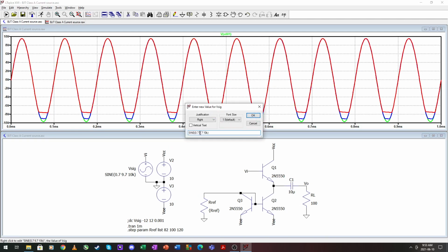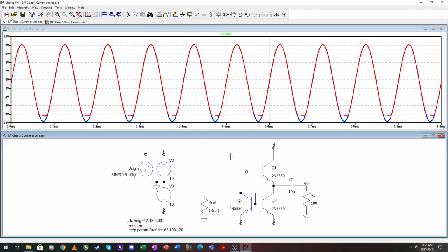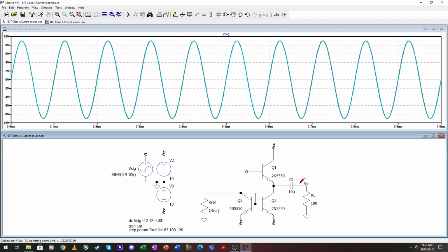And let's remove this DC quickly and let's make this 9 again. So there's our input, there's our output, and see the DC on our output of that 0.7 has been removed due to this capacitor. Okay, but I think it would be best to do the DC removal here on the input side, a DC nulling of sorts.